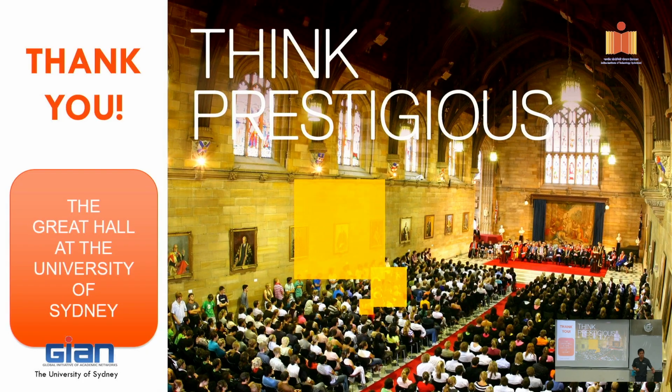Yes? So when we do a finite strip analysis, there are certain cases where you will not get a specific minimum for local or distortional buckling. Yep. So in that case, how will we account for that? That's a really good question. One approach which we have seen, we need to run a constrained analysis, take the minimum of that, take that buckling load, then extrapolate. Yes, that's good.